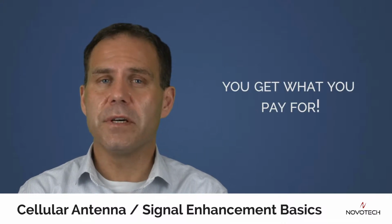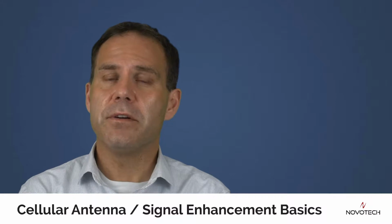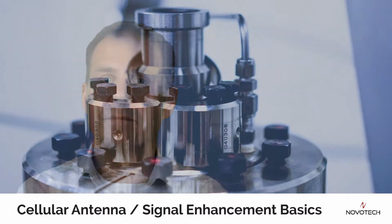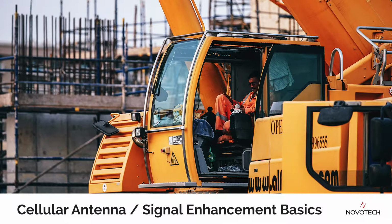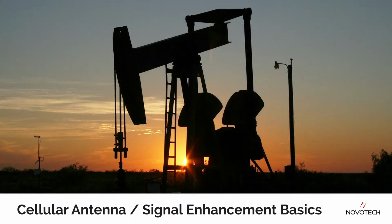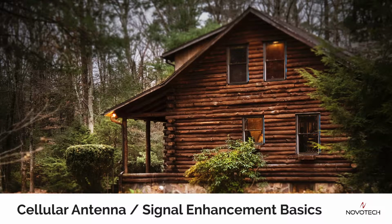A lower cost device might seem like a good bargain at the time, but they often just end up amplifying noise more than they do help with the signal. To keep it simple, here are three different categories of boosters: inline, area, and mobile. Inline boosters are designed to provide signal enhancement to a single device. They are commonly used in low coverage deployments that are more rugged in nature, such as on an oil rig, at a remote weather station, or at a modem deployed at a forestry site.